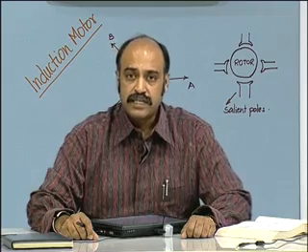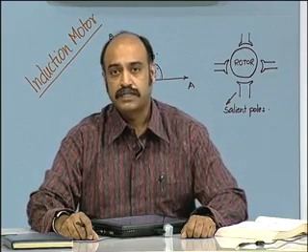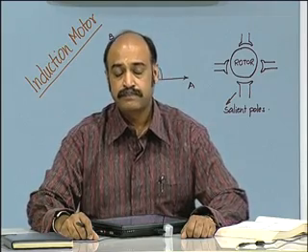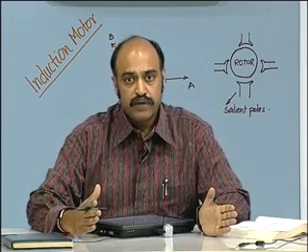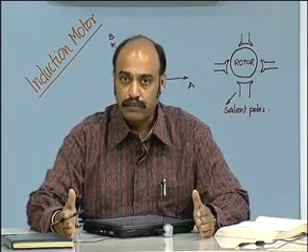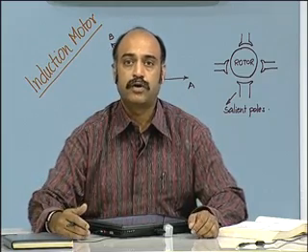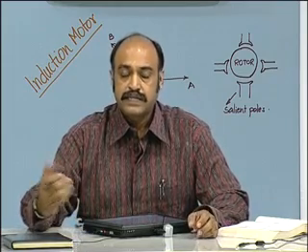So we began our discussion by an initial comparison of the induction motor with the three-phase transformers. In the case of three-phase transformers, we had the energy movement from the electrical side into the magnetic domain and then back again into the electrical domain in the secondary.